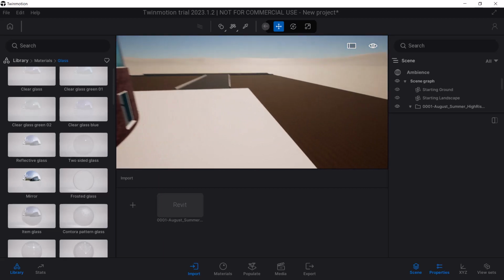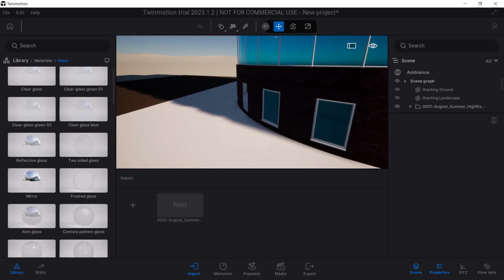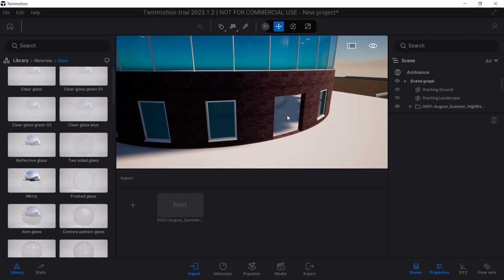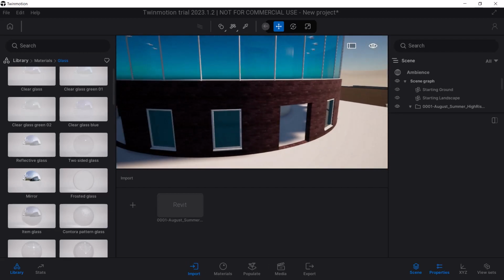From the model, you can see the ground that is supposed to be earth, so it's using the Revit materials to do that. You can also see that I do have my door opening instead of a traditional door from Revit, and I'm going to explain why in a little bit, why I did door openings instead of normal doors, and windows, like we did with windows.